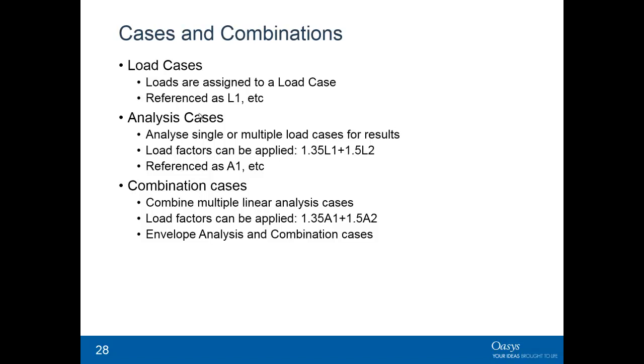They are actually separate because in analysis cases you can do load factors and load combinations within the analysis, and the analysis case can be set up to give multiple results. Combinations themselves, you can combine multiple linear analyses together, but it's not appropriate to combine non-linear analyses together. And you can apply load factors if appropriate, and then you can envelope the results as you see fit.